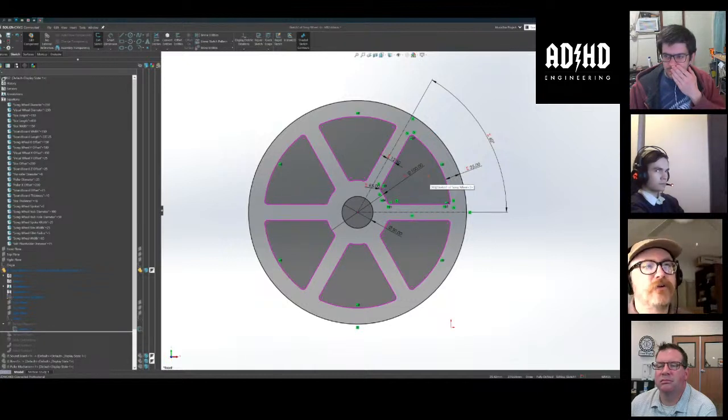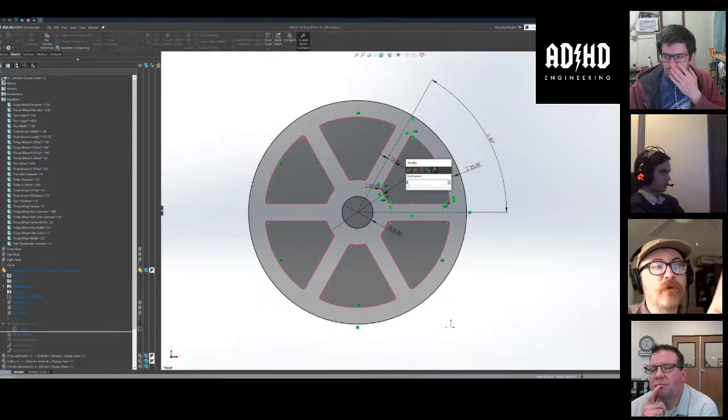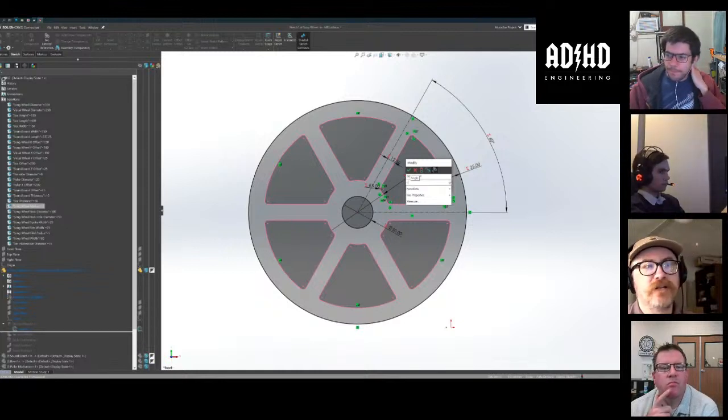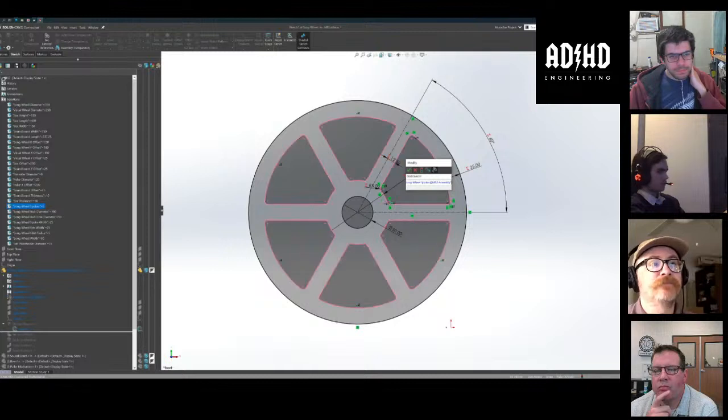Well, if I double click that, bring this up, and press equal, it's important to do equal, because if you don't, it will grab this number from over here but won't save it as part of the equations. It'll just pick the number that it is now. So you want to make sure you grab it from here, like that. And see how it's blue and in quotations? Now you have applied it, and it's live. It will live in there.